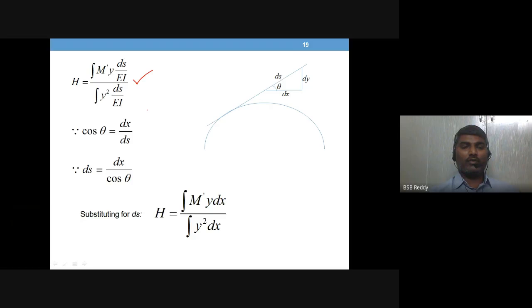Okay, now in case of circular arches, what we have done is we have converted all these Cartesian coordinates like y and ds and x, everything, x in m dash where we write beam moment. So all those Cartesian coordinate values you have converted to polar system, which is r and theta. Right. Now you are taking up the parabolic geometry, where the geometry is a parabola.